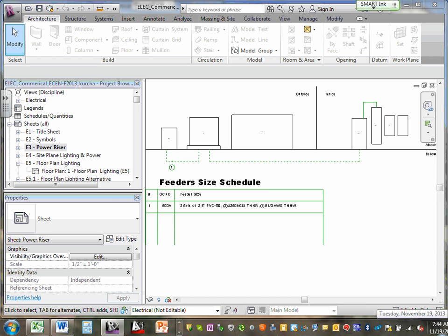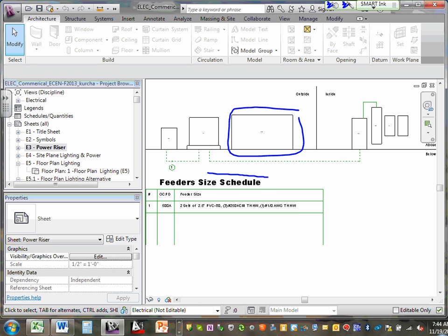So, Adam, if you remember your riser, we brought that from the transformer, guys, to the CT cabinet all the way to the auto transfer switch. Then we have a big fat generator sitting right here. Now, when you did the feeder schedule, you remember that? I told you to hold on the generator until we size this generator. We can't predict what size it would be, but we're going to hold on that one.